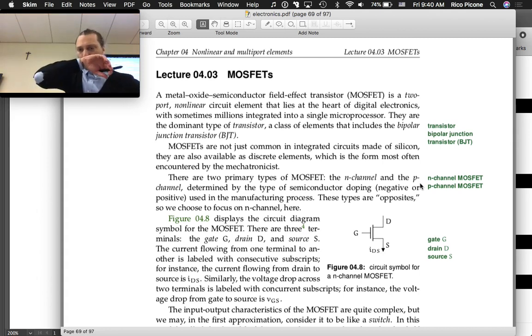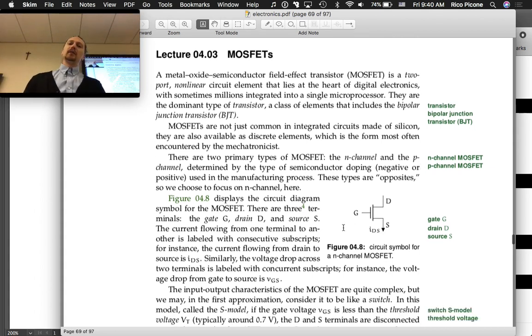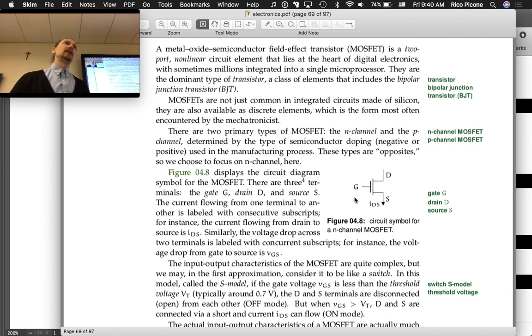MOSFETs. I covered it just slightly at the beginning, but the idea was that if you have a small variable signal, you can connect it to the gate. This is our typical application, but other applications for MOSFETs we didn't really discuss. Mainly, we want to be able to take a microcontroller or something that has a variable signal that we can control, but that can't supply a lot of power, and we want to supply a variable but powerful supply to a motor or some power-hungry device.